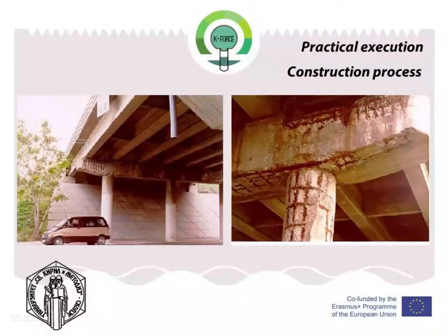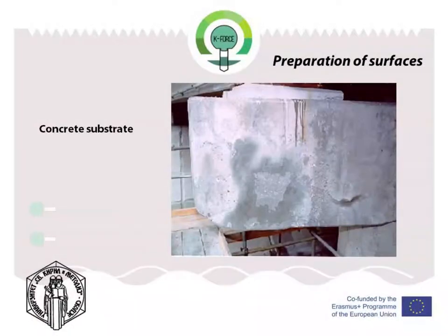Wide cracks may need sealing by means of injection. Any cracks wider than 0.2 millimeters should be injected by suitable, compatible low viscosity resin to fill and seal the cracks. To provide an adequate bond with the adhesive, the preparation of the concrete substrate should be carried out well. The substrate should be roughened and contamination-free in such a way that the concrete quality can be utilized in an optimum way. This is done by means of high-pressure blasting or grinding.